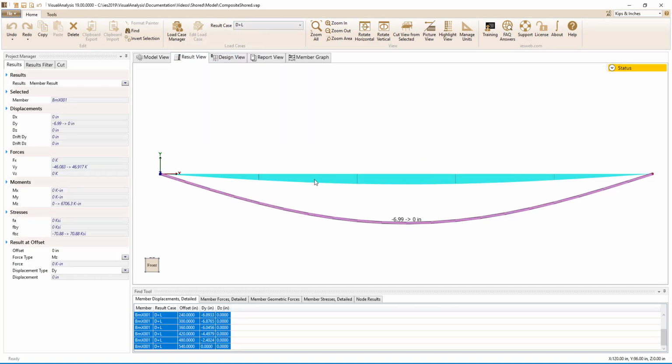The deflections for these analysis results appear large since they were computed using the moment of inertia for the non-composite beam. Prior to performing the deflection checks, these results will be scaled by the ratio of the beam's moment of inertia to the lower bound moment of inertia to account for the composite stiffness of the beam and slab system.